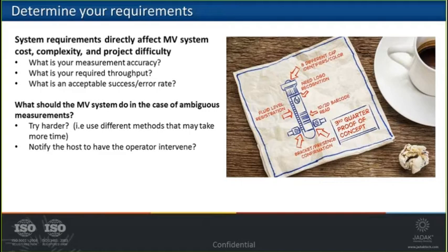That's all going to determine what kind of camera, with what kind of resolution we use. What's your required throughput? As I mentioned on the slide way back in the front with industrial machine vision, if you want a result every 100 milliseconds versus a result every second, of course that's going to regulate what kind of processing system you have to have connected to that camera.